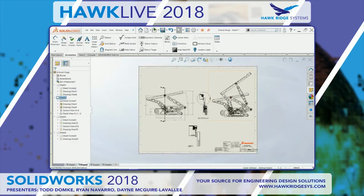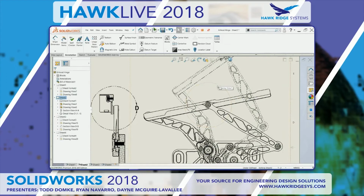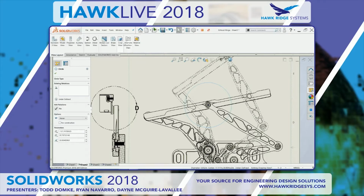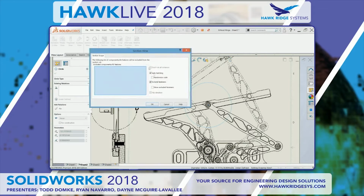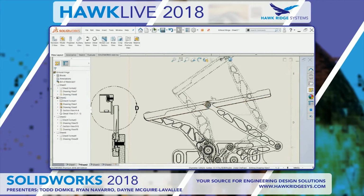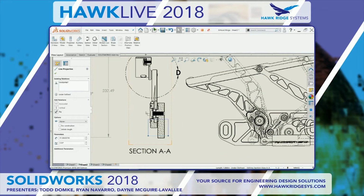So on my final drawing sheet here, I have this alternate position view, but I want to make a broken out section to try and fit as much detail as I can in one small area. So now I have the ability to do that. So I can make myself a broken out section of this alternate position view. So I have this section view here, and I'm going to give myself a broken out section of this section view.